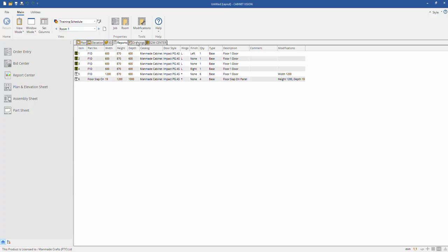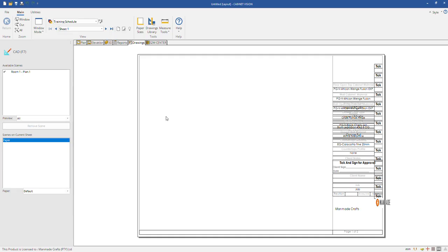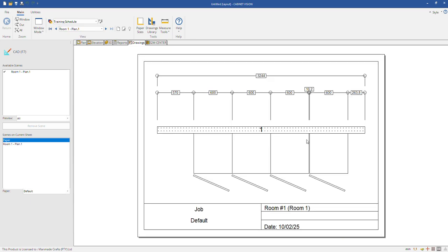Now what that does is if you go to your drawings, it's in already. Go there to the drop down on top where it says sheet 1. There's going to be a new sheet there. And there's your plan sheet. The elevation sheet does exactly the same, but for your elevation view on that specific wall that you selected. So that just sends you a quick little plan elevation sheet through that you can then print out and use for your designs. Okay.